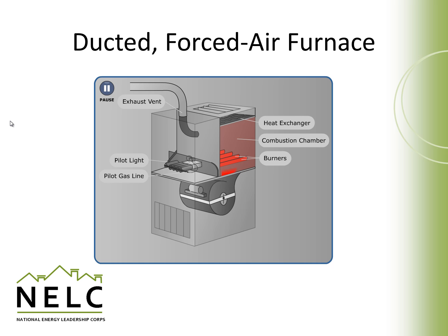And when the fan comes on, it begins to circulate air across the combustion chamber and up through the ducts in the house. If you remember in our discussion about air leaks, these units will draw air in from the house and force it through the house, and can also result in pressurizing the house and can contribute to air leaks.